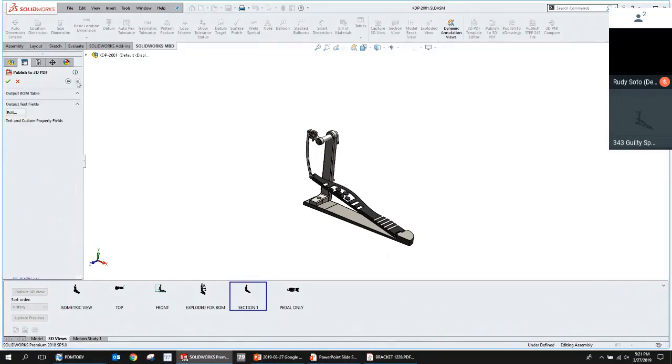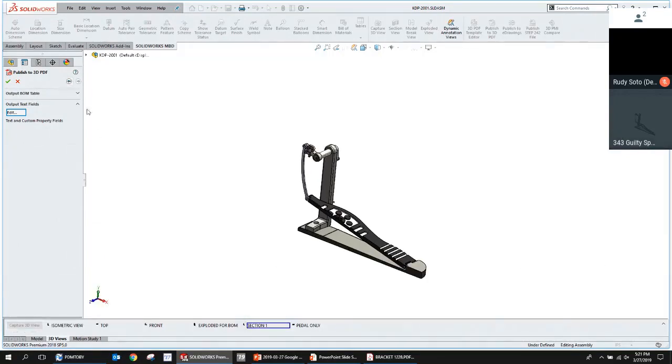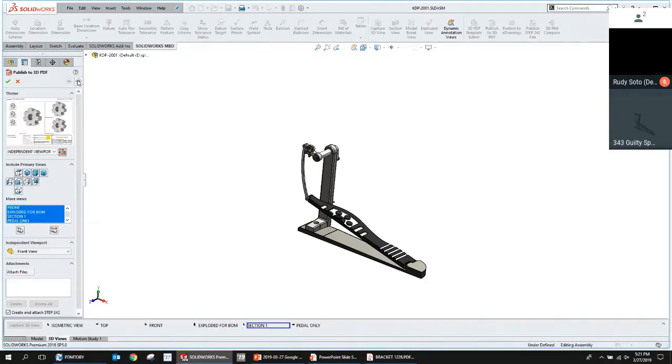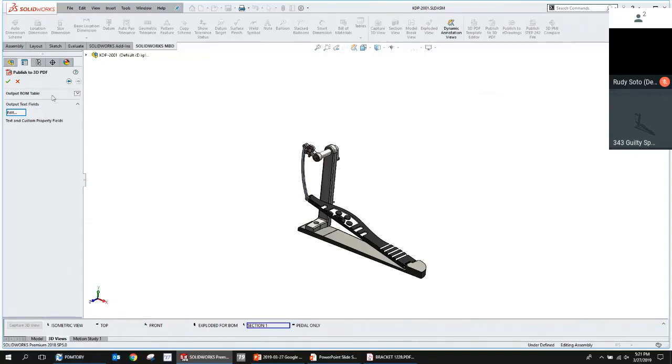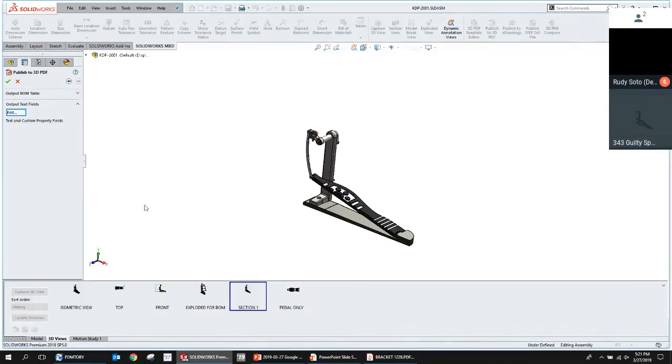Then when I go to page 2 here, I can control what's going on with the bill of materials. So you'll see here, there should be an option here. What I'm expecting to see is an option that says what information in the bill of materials you want to include in the table. Basically, I can uncheck the option for description since description wasn't showing up. I'll have to double check why that's not flying out. I think it's just being funky because it knows I'm demoing.